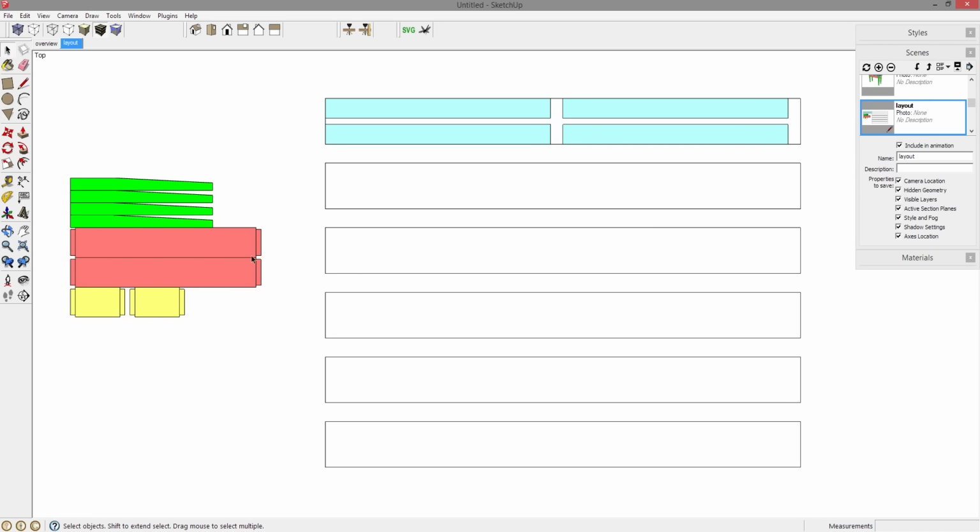So let's work on the next pieces. Let's go with these legs. Now, take into consideration these legs are 2.5 inches square. This lumber is 1.5 inches thick, so it's going to take 2 of these shapes for one individual leg. So instead of 4 being represented over here, I need a total of 8 of these represented over here. So let's M for move and move this down into place.